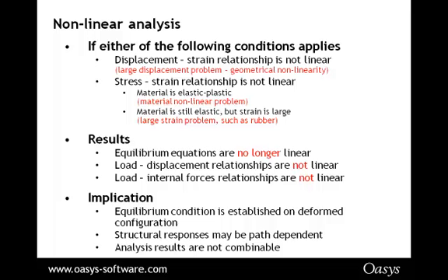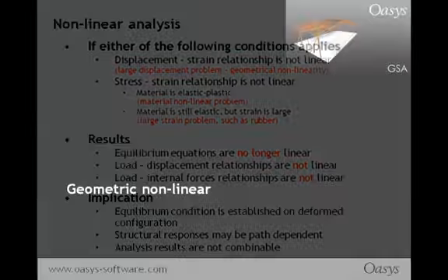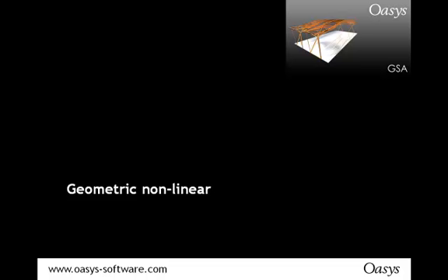End result, equilibrium is on the deformed configuration, deformed geometry. How the loads move through the structure can be important, and the analysis results are not combinable. More of that point later. So, nonlinear covers a variety of effects.